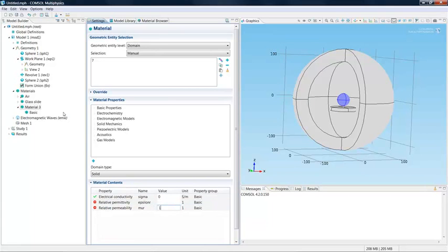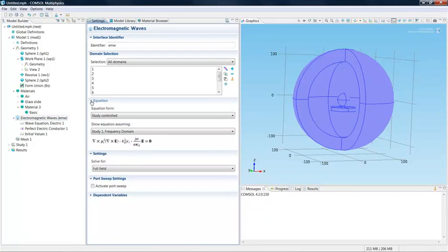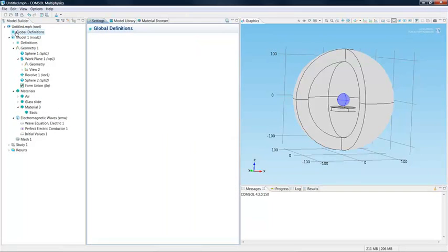The biggest effects are going to come from the relative permittivity. And the relative permittivity, if we look at the equation, so if we write an imaginary part, it's this same thing. It's conductivity divided by the frequency. So once we input the imaginary part of the epsilon sub r, then we don't need to put the conductivity, otherwise we will be inputting things twice. So that's why sigma is 0, because it's going to be here. In epsilon r, we're going to put an imaginary part right away. So then we have to define that.